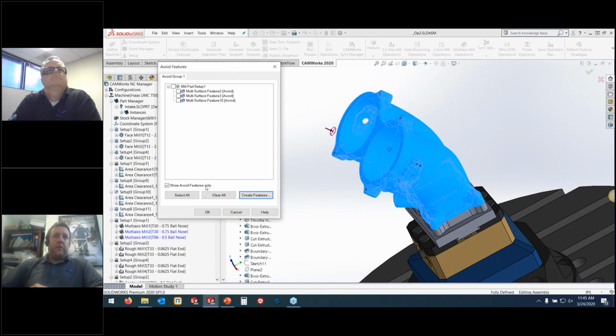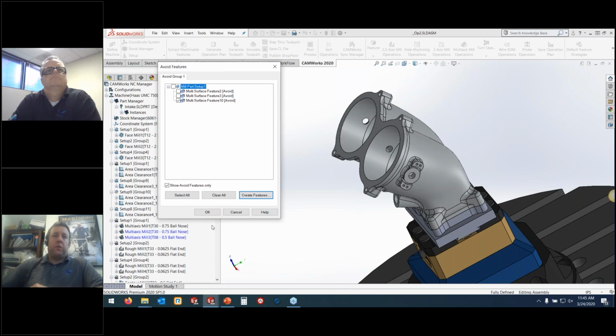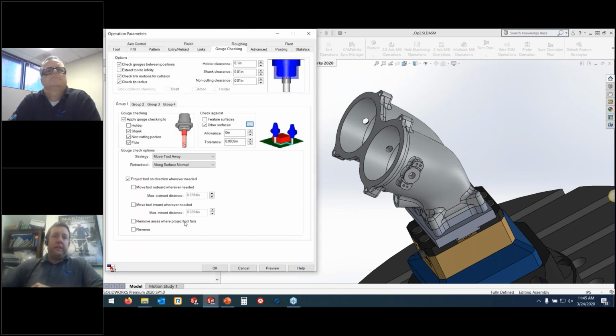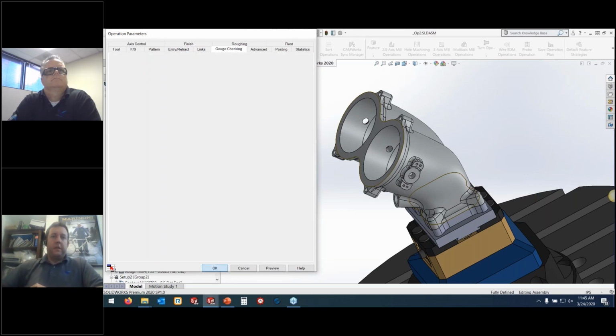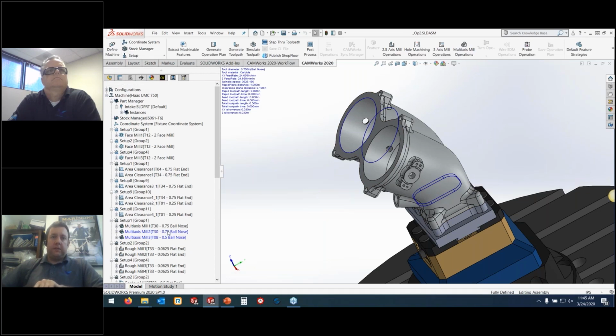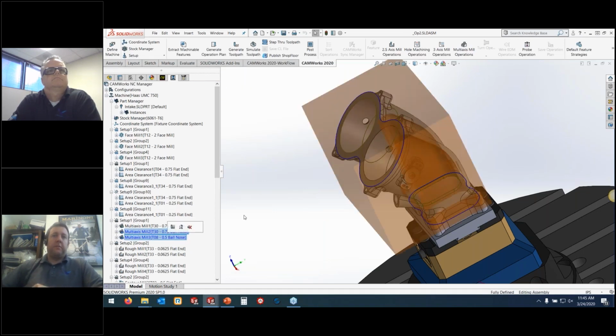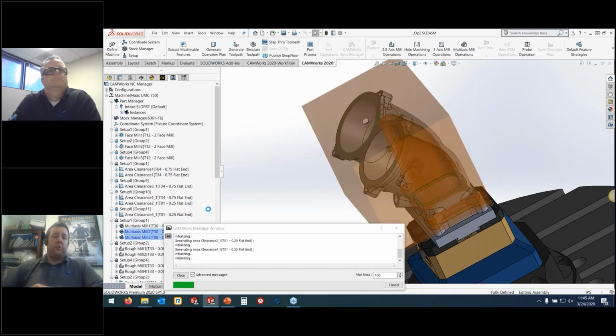So in here, we're telling it to use the gouge check to go in and pull the toolpath out from that surface wherever it needs to occur. And then this is where we can control that. So rather than tilting the tool this way, we're using the gouge check and actually forcing it to gouge and pulling the tool out along the tool axis, basically. So we can get those kicked in and get them being generated, and then we've got our program done. Our order is nice and clean, and everything else is ready to go.